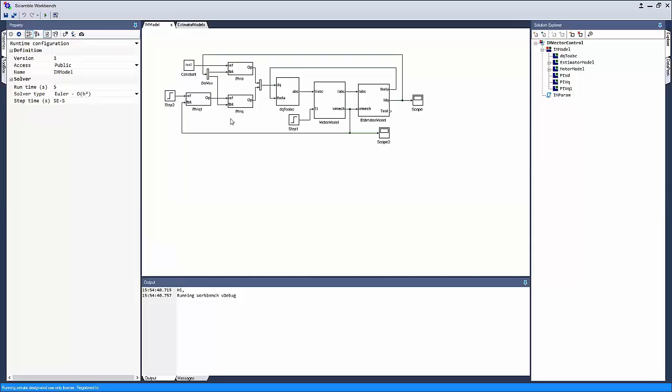It's always going to be phase shifted by 120 degrees. So you essentially have just two control variables. And by using the alpha beta transform as well as the DQ transform, we have converted those two control variables into VD and VQ voltages as the control variables, which in turn allows us to control the ID current as well as the IQ current.